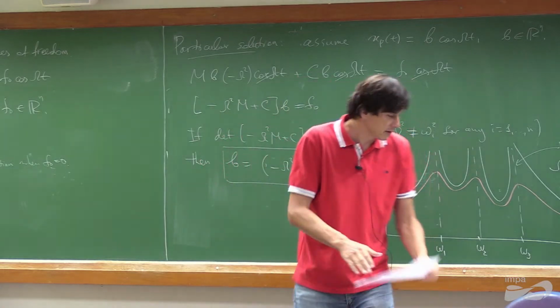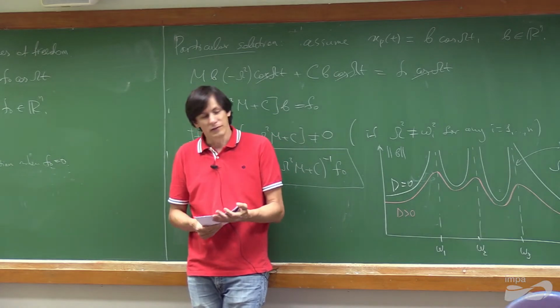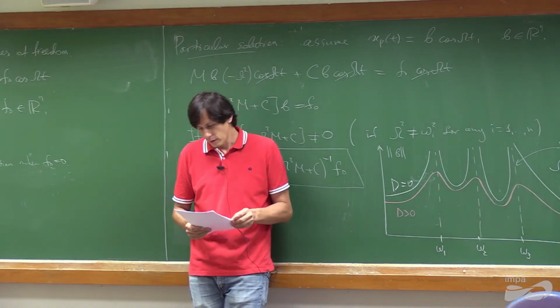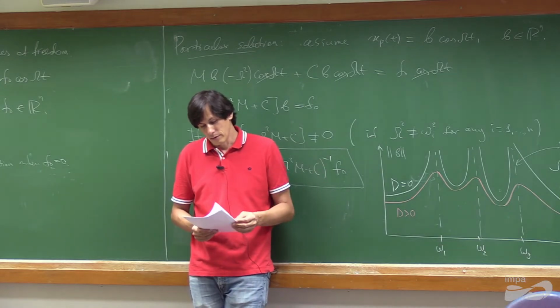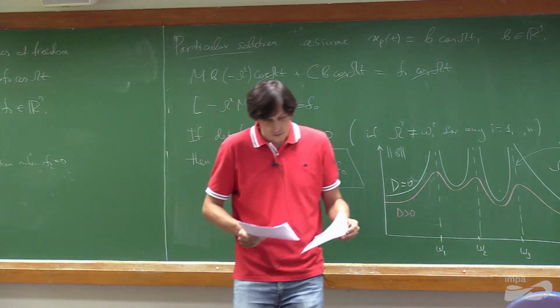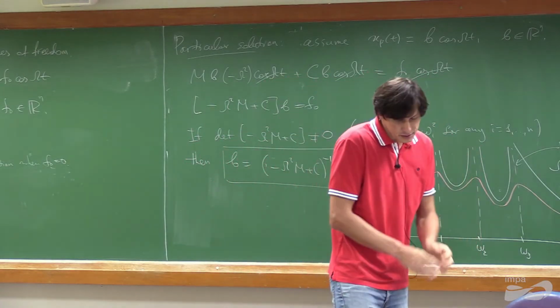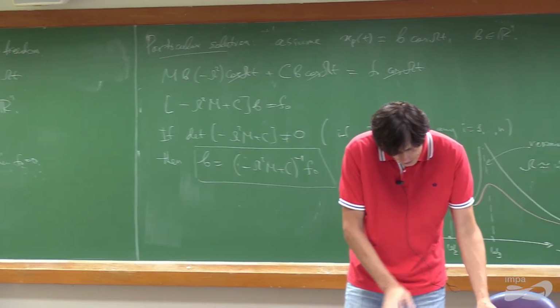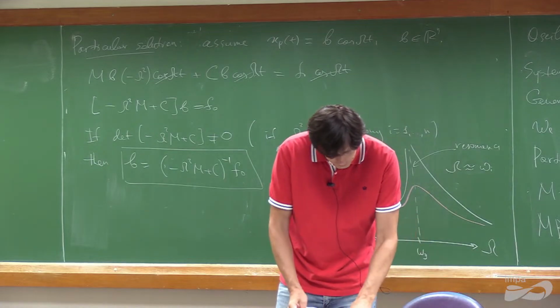So that's how you avoid resonances. And in particular, this is why the analysis of the eigenfrequencies is a very typical test in engineering, because knowing frequencies, you know how to avoid resonances or how to be in the resonance, because sometimes we may want to be in the resonance. Okay, so this is the end of this part, which I think is simpler.